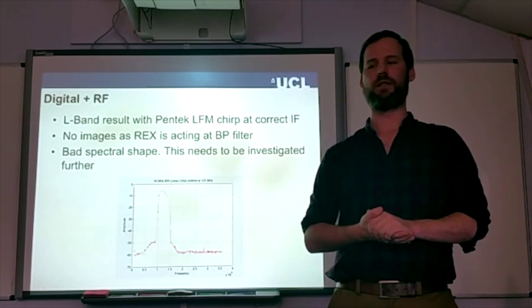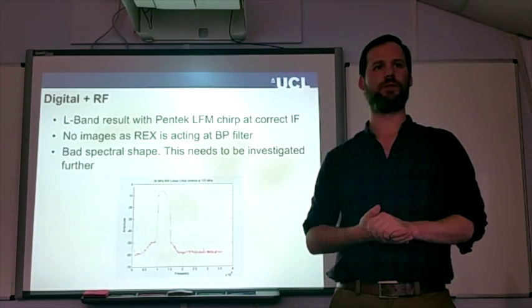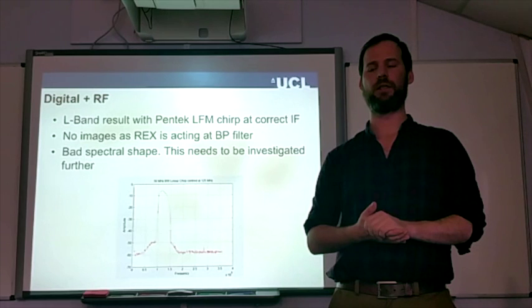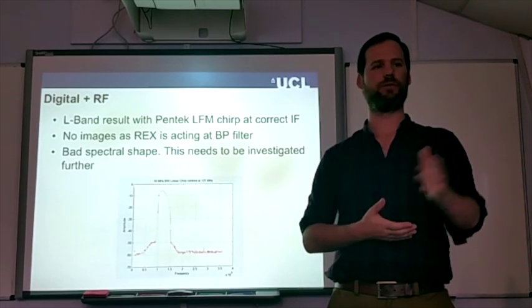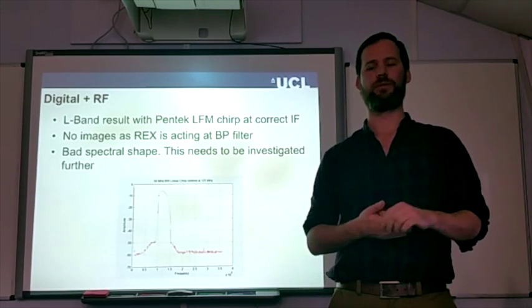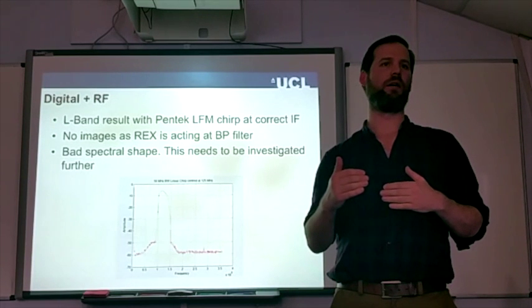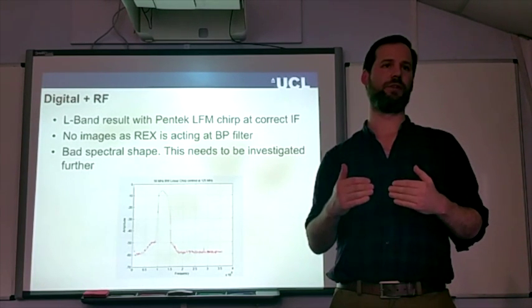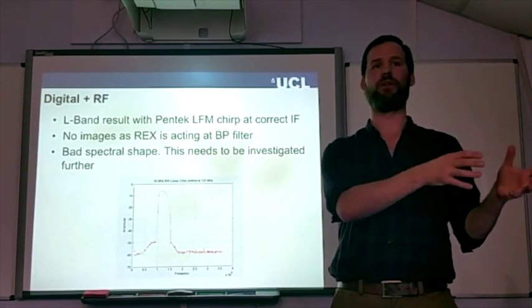Yeah, we need to look at the match filter response of the signal as well, after putting it through our. Well, we may decide not strictly to match filter it. There may be some further tapering to be done there, which would improve it. Yeah, I think another part of the compensation which Francesco brought up was perhaps putting a higher weighting on the higher amplitude components of the signal in your generated chirp in the first place.